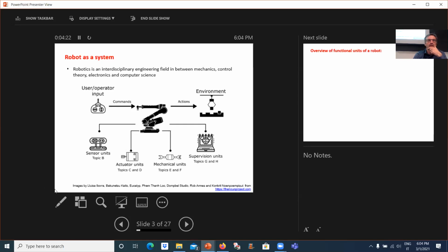Or, for example, you have a graphical user interface or a joystick, and you can provide high-level commands with a joypad. We do this with our quadruped robot. We have a joypad and we just give high-level commands: go forward, go left, backwards, rotate in place, and that's it.